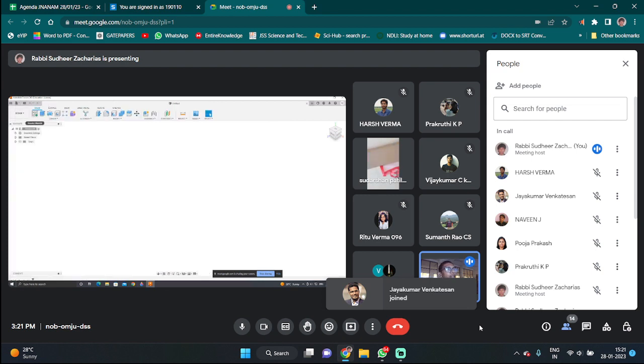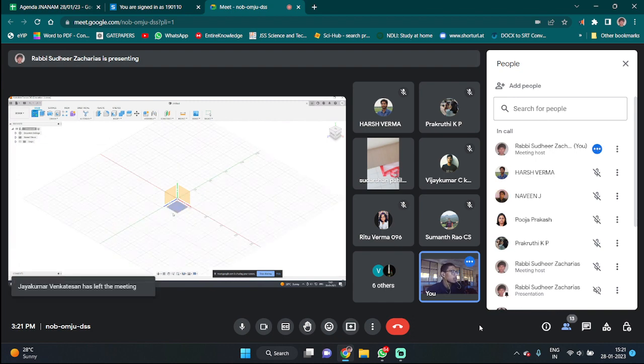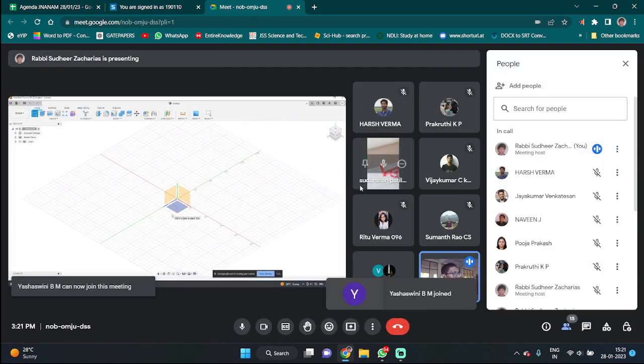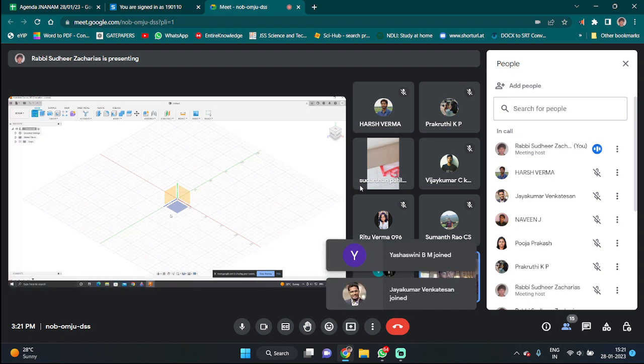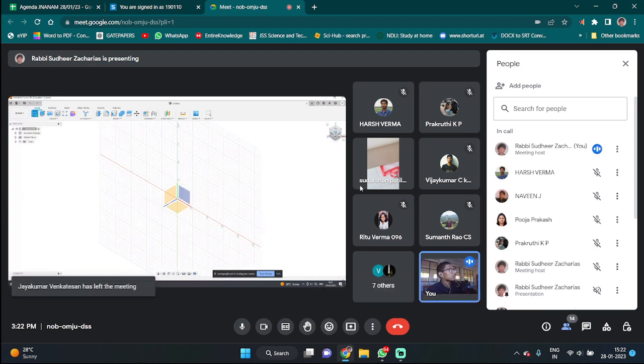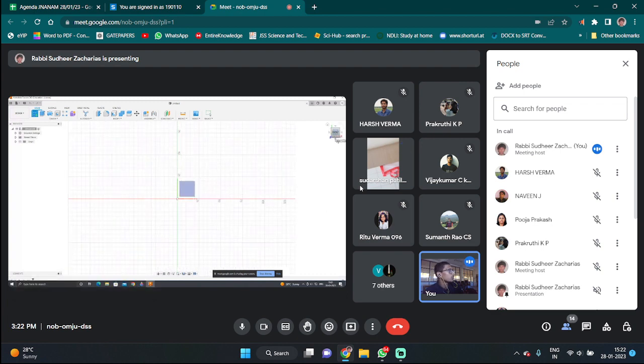So first we need to select a plane of our choice. There is the xy plane, yz, and then xz planes, right? So where we want to draw our first, for example, if we are creating the 3D model of our phone, we can select the bottom plane over here. Top right, you can just see the legend here. So you can select front view. This is the bottom view. And then you can click home to just reset your vision.